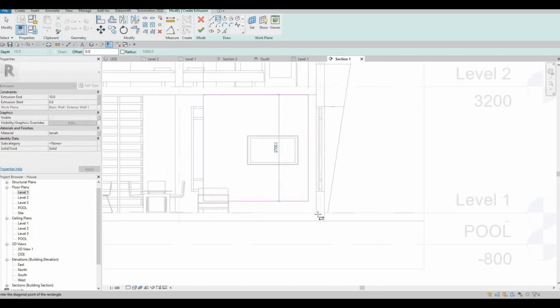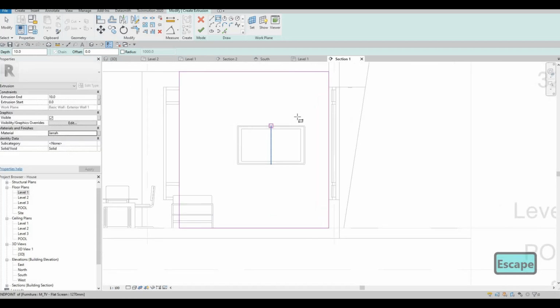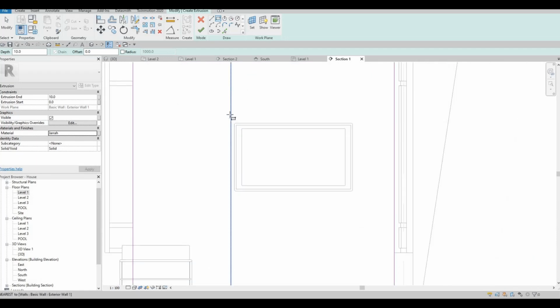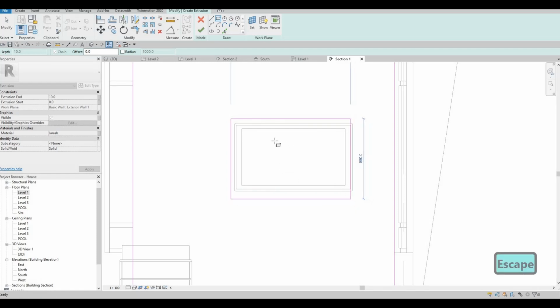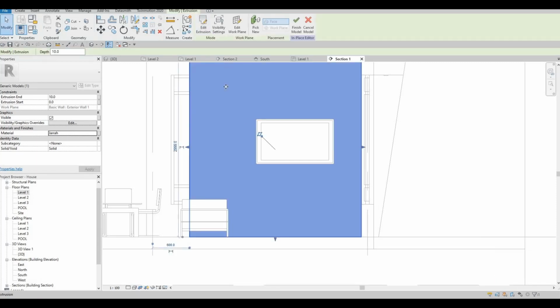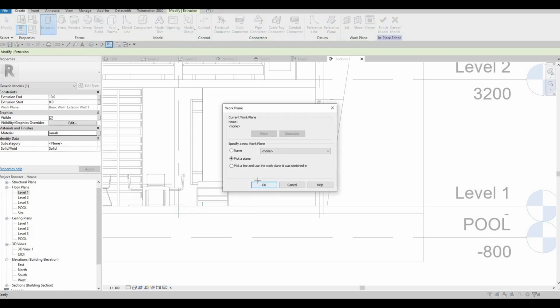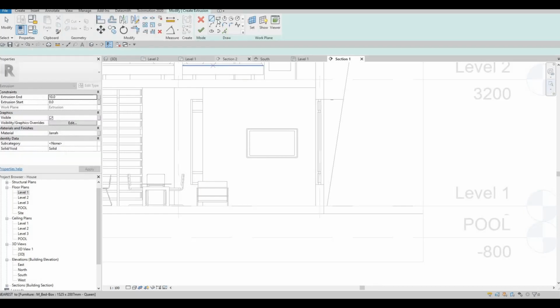What I'm gonna do is create something like this, because I could play around with the wall, all of the walls right here. I'm going to add, I'm gonna make this one as my back, so a wood like that, and then another. So good thing I already have 10 there, so it's just extruded 10, so it's very thin. Create an extrusion, pick a plane, and then select this one.